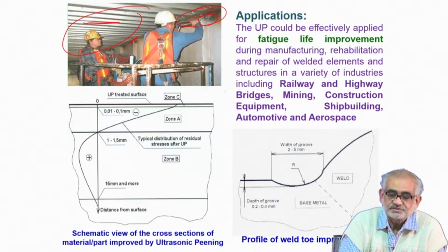So in order to extend the life of such welded joints at these difficult to access corners or large surface areas and so on, all you need to do is to take the ultrasonic pinning gun, and then treat the surface and create this state of stress.